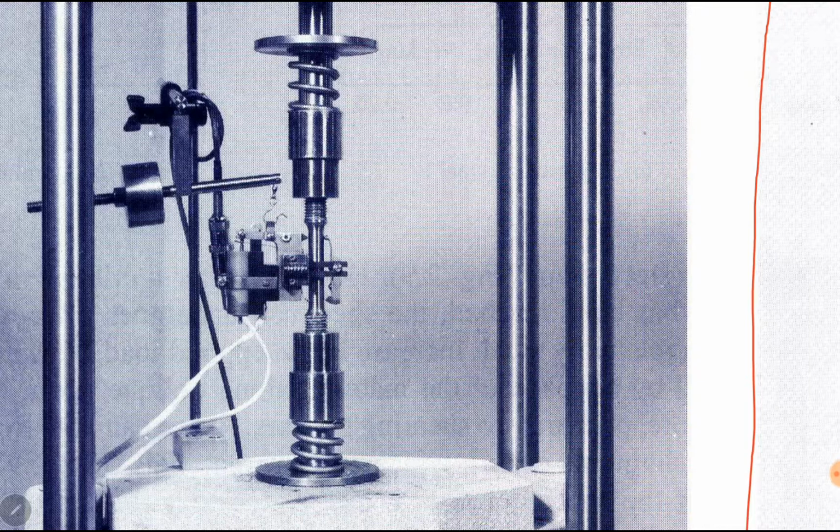So whatever the number of loading cycles are, the steel 1020 HR will not fail below 30 KSI. For example, at 10 KSI, if we draw a line here, it will never intersect this curve. So this 10 KSI is below 30 KSI, and the steel 1020 HR will never fail at 10 KSI even at infinite number of loading cycles.